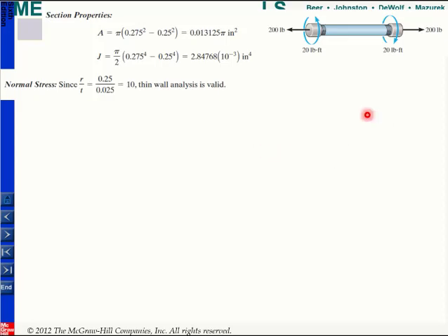Okay, and in this case, basically I want to find my stress along the pipe direction. So I want to find my longitudinal stress, but I also have some additional stress due to this applied load. Which means that if I find my stress along the longitudinal direction, it will be equal to N over A plus my longitudinal stress.